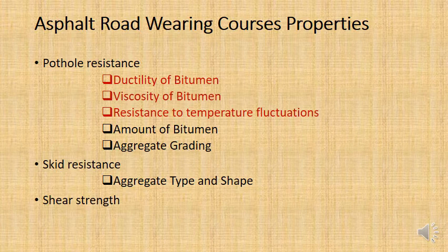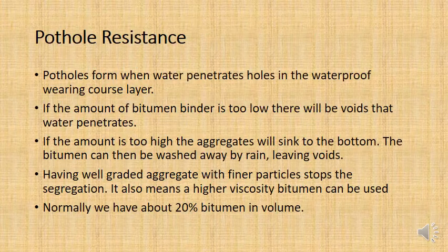And then finally, shear strength. If a car is driving at high speed and then brakes suddenly, will it break aggregate out of the wearing course, out of the asphalt surface, because of the inertia energy, the shear force being applied to it? You want shear strength as well.